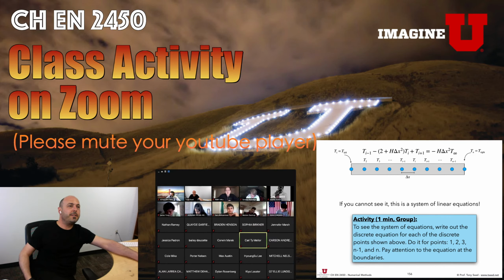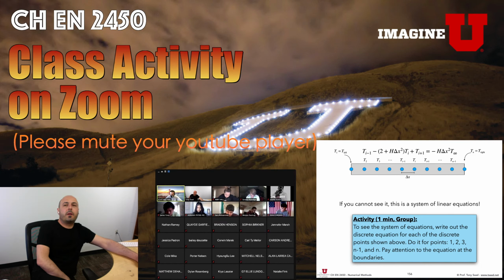All right, any takers? Can I try, Professor? Go ahead. So T0 minus (2 plus h delta x squared) times T1 plus T2 equals negative h delta x squared T infinity. Okay, I'm going to stop you there.